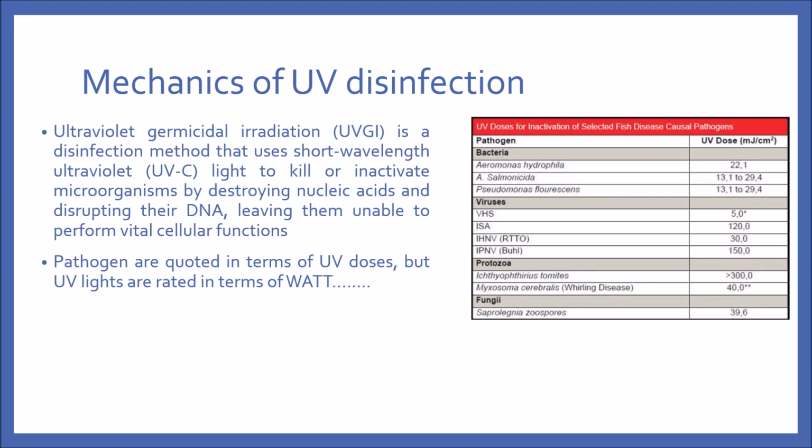However, it is confusing as the bacteria require certain UV dosage manifested as flux. But if you were to talk to the suppliers on sizing UV, they typically give you a benchmark of 1 watt per 1 meter cube of water. However, this is just a rule of thumb, as the UV light voltage does not give an indicator of how much UV dose is actually reaching the pathogen.